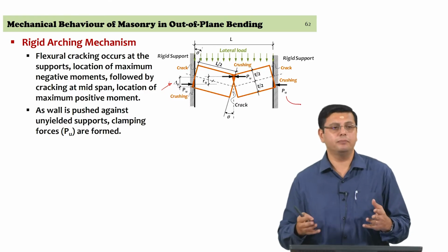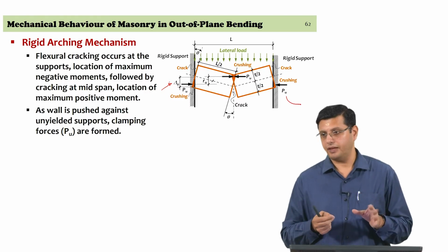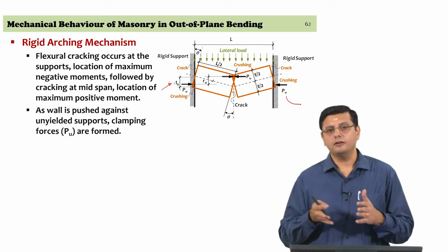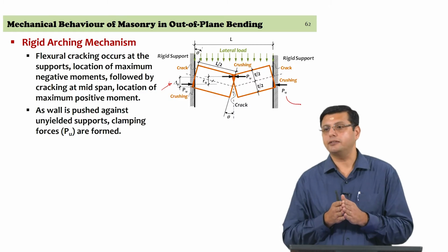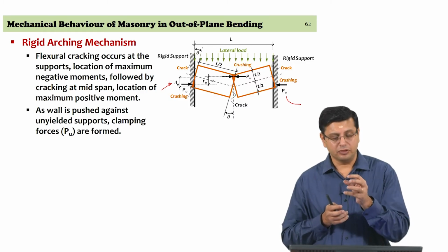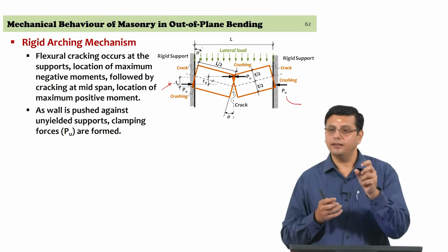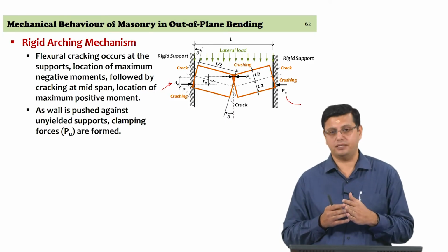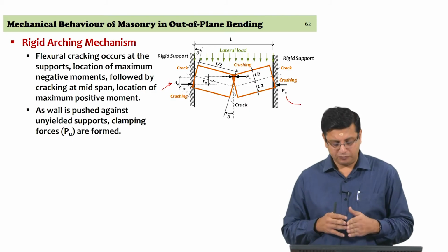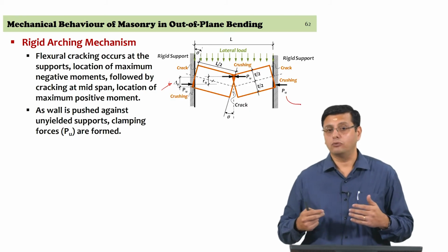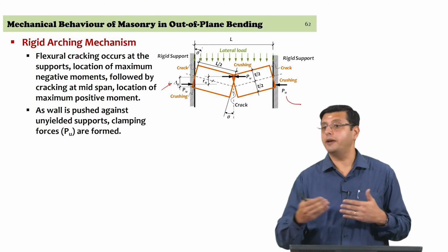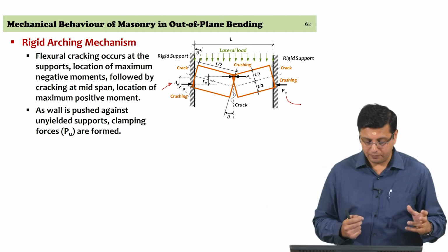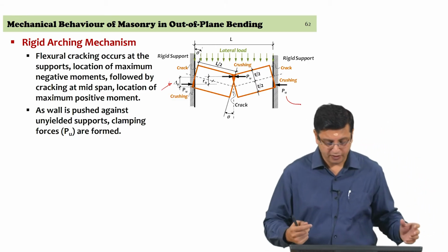Of course, that is going to be dependent on the material strength, and the material strength that we are talking about here is the strength of masonry, but at a joint you might not have the unit and the mortar acting together. It might simply be the mortar in a joint. So, it could even be the mortar compressive strength. So, we will have to make an assumption on at what stage how much of length is going to be available as a contact for the wall to develop the maximum clamping force available.